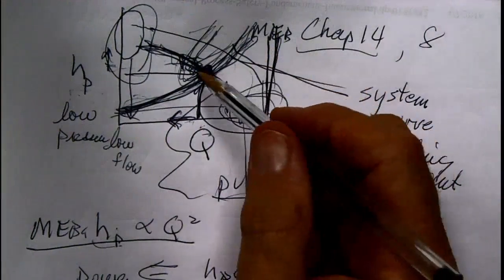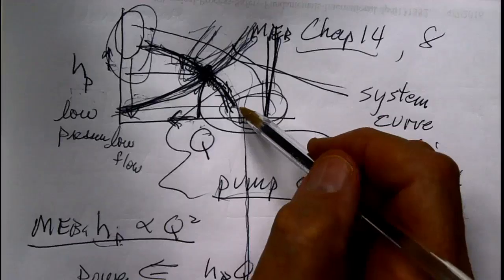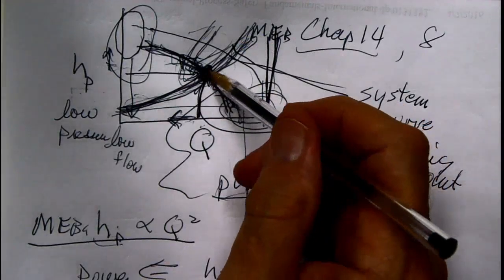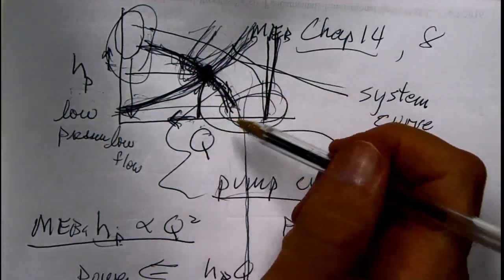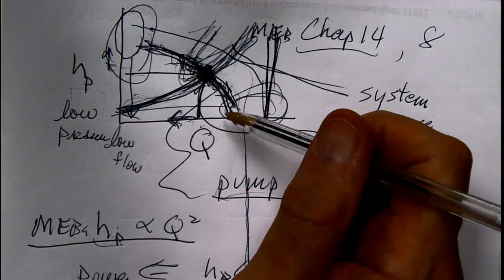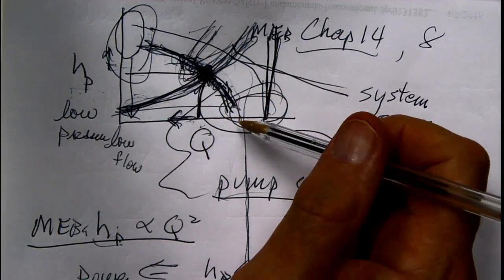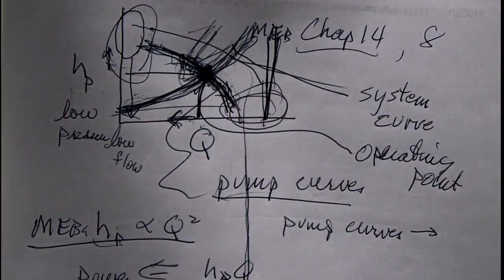One of the worst problems that I've ever encountered was to integrate up a pump curve while determining how much cake was being formed in the filter press. Now, you do one of them there calculations, a filter press with the variable pressure drop building up over time, flow rate being reduced, and the pump head going up.